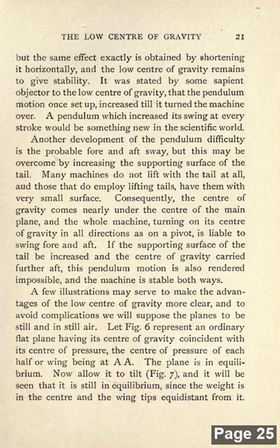A few illustrations may serve to make the advantages of the low center of gravity more clear, and to avoid complications we will suppose the plane to be flying in still air. Let Fig. 6 represent an ordinary flat plane having its center of gravity coincident with its center of pressure, the center of pressure for each half or wing being at A A.